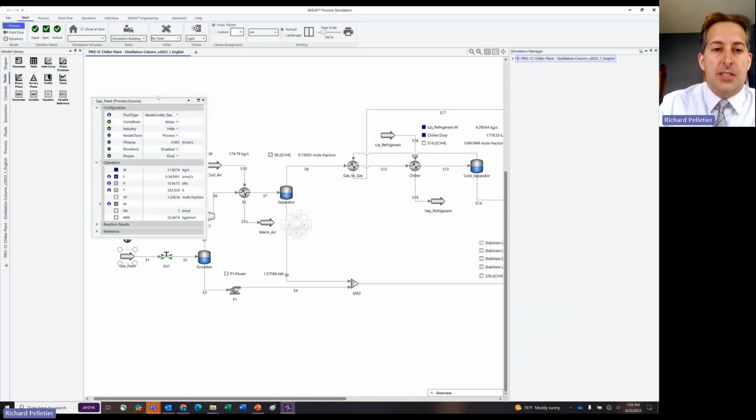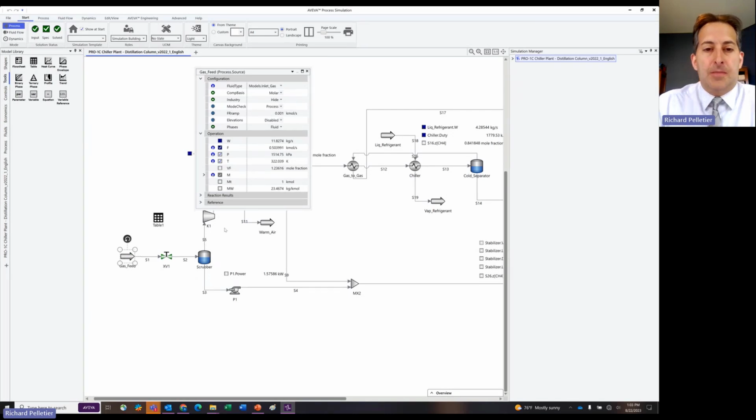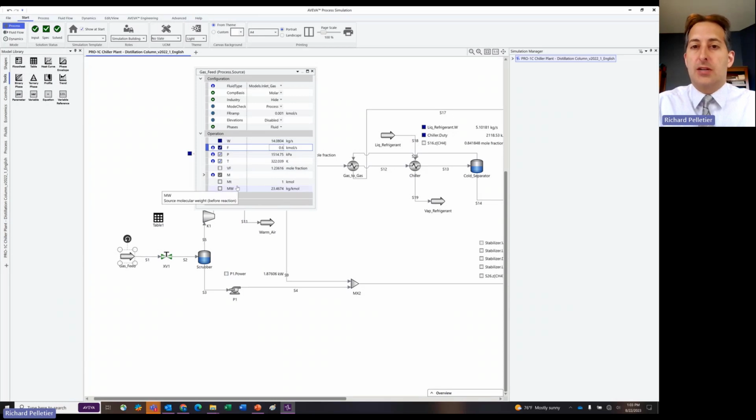Right, so when I come into this mini property inspector and I change a value here, and I see mass flow rate update, that's because the program has already run, it's already solved, and it's already updating all the different calculated information throughout the entire simulation with the updated results. So this is an output. This is a result that I'm looking at. All right, so I'm getting my output in the same area that I'm also using to do data entry. And this is throughout everywhere.